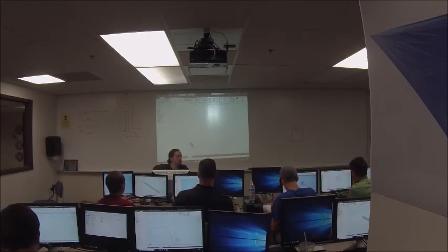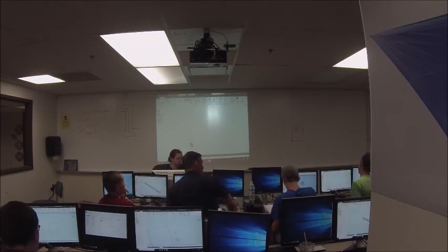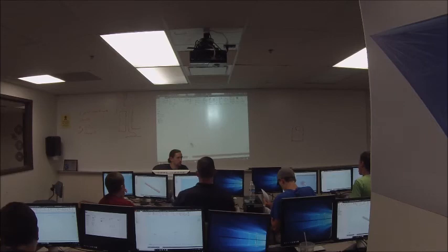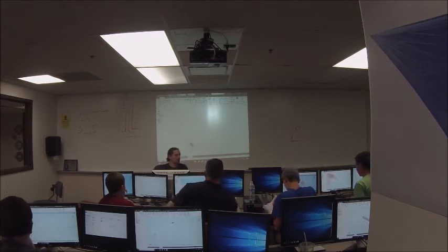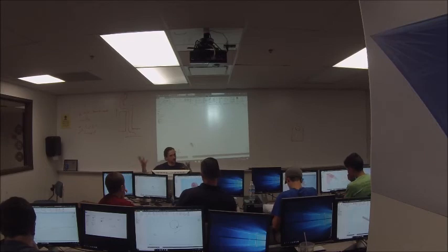Yes. So if the shape is purple, that means it's not fully constrained, right? Is there a way to tell which things still need to be constrained, or do you just have to look and figure it out? You kind of look and figure out. You can click and drag on stuff and see what moves. That's often helpful. If you click and drag on something that's not constrained, it'll move when you click and drag. So clicking and dragging and seeing, oh, it slides in this direction, but I can move it this way, that will help you figure it out.